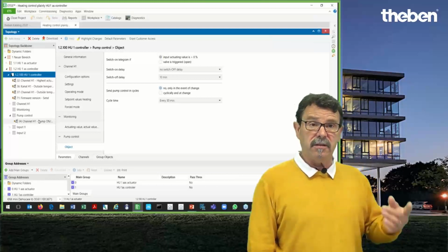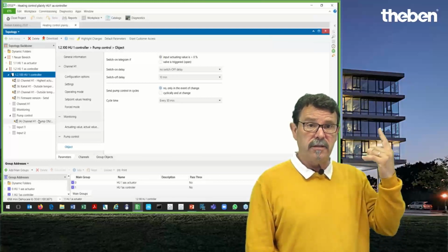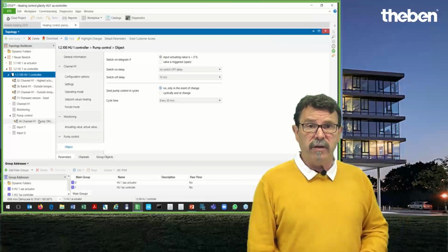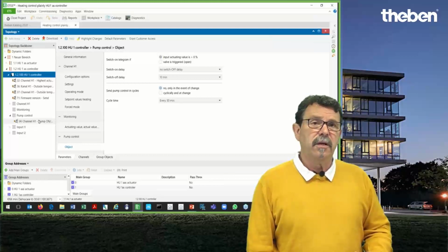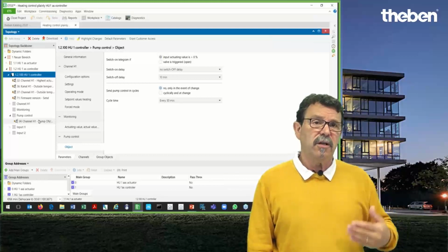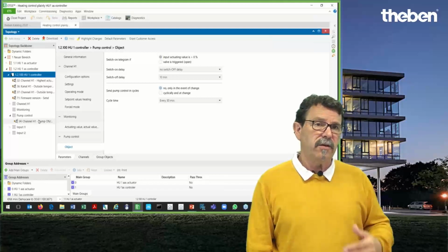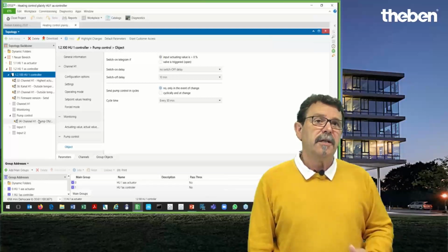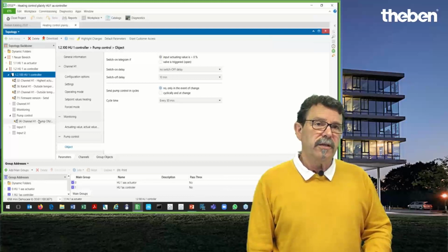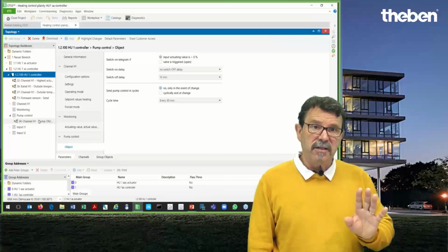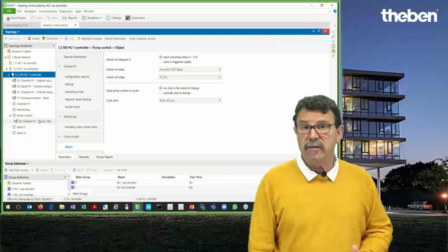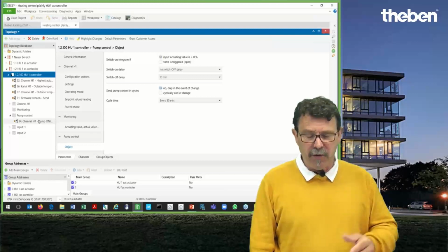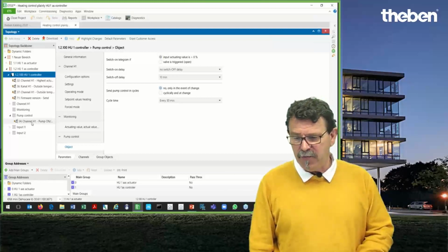If there is no demand in such a room, like here, for instance, lights are dark, nobody there, so why in this second floor shall the heating system be activated, why shall the heating pump move or bring the warm water into this entire circuit. Nevertheless, if the valves are closed or not, you can stop the pump as well and save additional energy on the heating pump side, if you want.